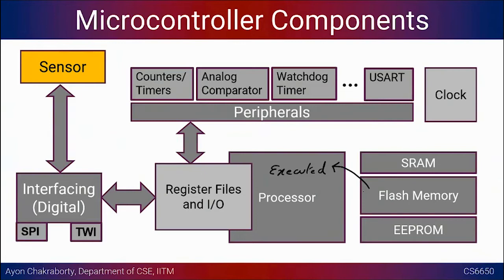And we also had this bootloader, which is a resident program inside the flash memory. In one partition, there is this bootloader, which is responsible for fetching the program from an external computer, right? It could be another microcontroller, or it could be your laptop or desktop, from where the program binary is fetched and then written to the application section of the flash memory, whatever is the resident application in our microcontroller.